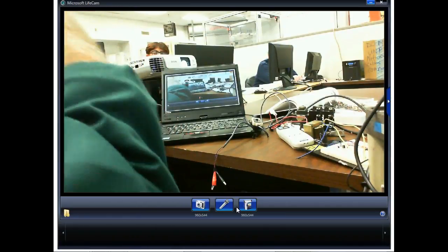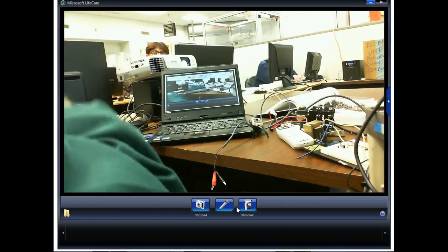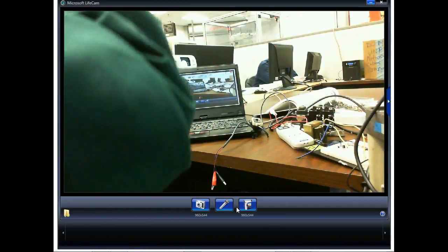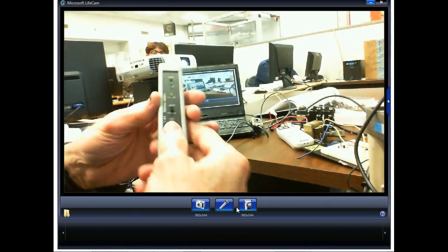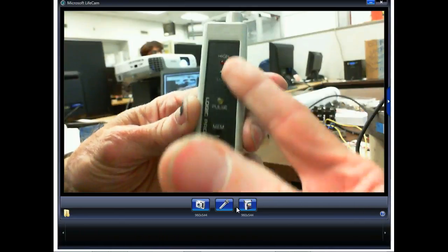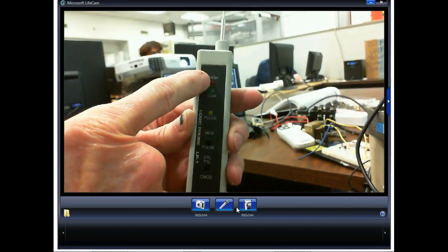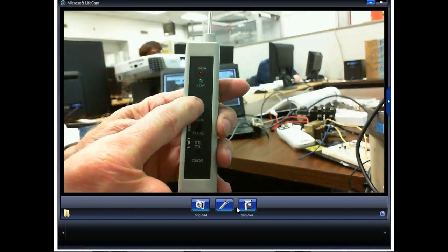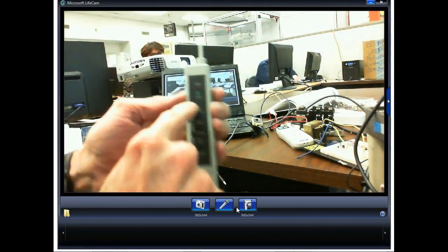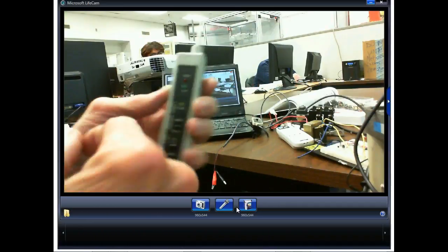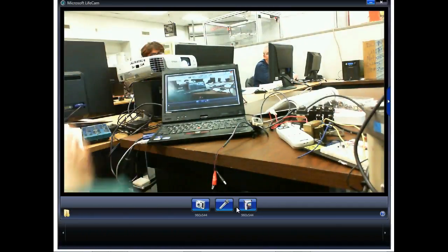So, the pulse goes through what we call a one-shot, which gives us a certain amount of time, no matter what the pulse is. So if you see a clock, all three of these are going to be on. If it's staying high all the time and you see this light right here blink at you, it means it saw what? It saw a negative going pulse. If it's staying low all the time and you see the pulse light blink, it means it's got a positive.